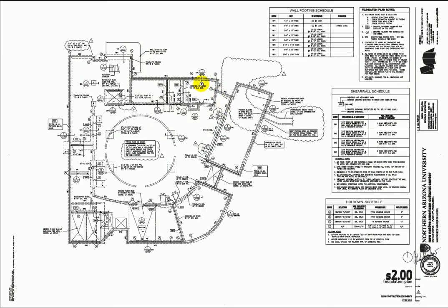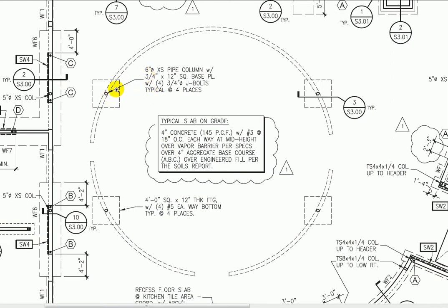So now I have a good feel that there are little strip footings around the perimeter. Remember from the general notes they had to be 2'6" below the exterior grade or the finished slab. In this case the exterior grade was lower. So that tells the contractor how deep to go. You'll note on the drawings it didn't give any elevations, which puts a lot on the contractor to figure out. So we got those footings. We have these little spread footings here. Let's zoom into the middle and see what's going on. So I see this one here looks like a footing.